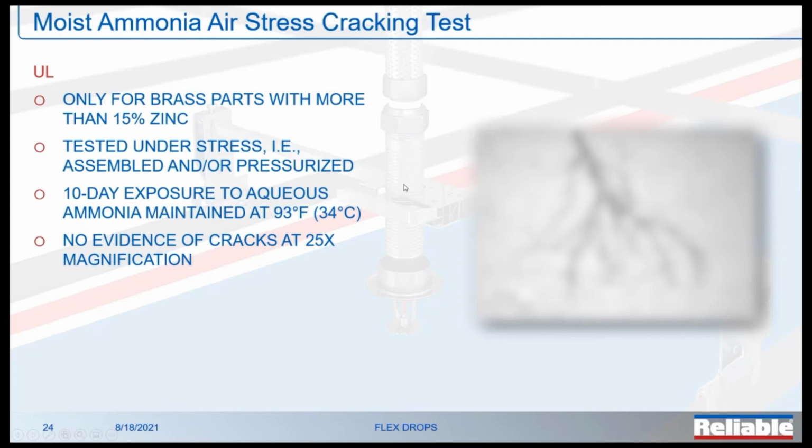Well, I'm glad it didn't crack the glass. And then what happens? You come out the next morning and all of a sudden it's an inch off of each side of that chip. And over the course of the day, it starts working its way out. It spiders out from that. That's another example of a stress crack, because that windshield is being flexed and expanded and contracted. And at some point, if it's got a breach in it, it's going to fail.